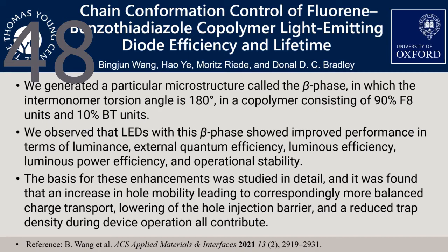We observed that LEDs with this beta phase showed improved performance in terms of luminance, external quantum efficiency, luminous efficiency, luminous power efficiency, and operational stability. The basis of these enhancements was studied in detail, and it was found that an increase in hole mobility leading to correspondingly more balanced charge transport, lowering of the hole injection barrier, and a reduced trap density during device operation all contribute. Thank you very much.